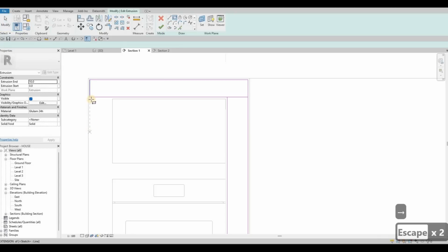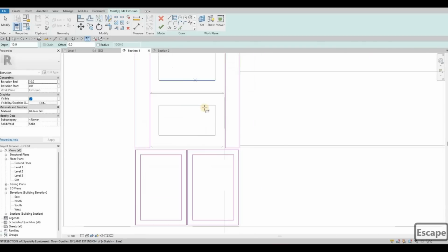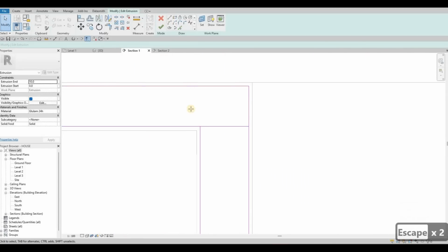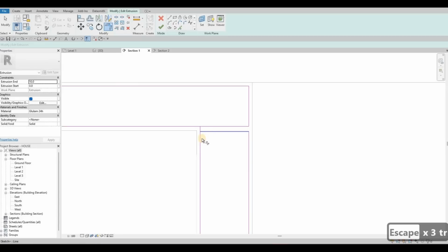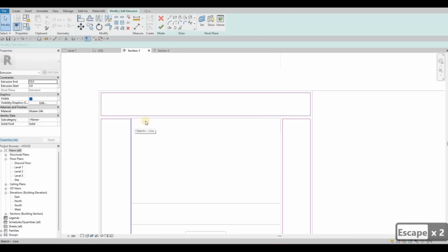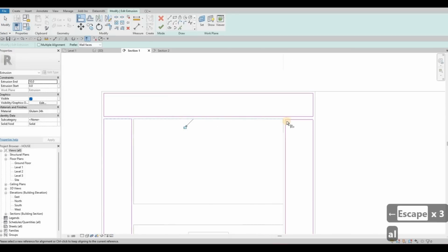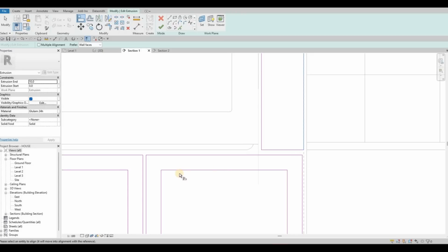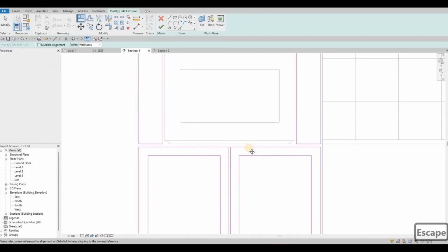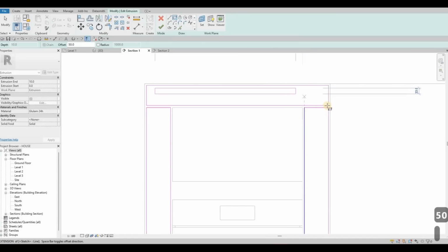And then now I'm going to add this one right here. Then I'm just going to align it all together so that it looks nice. And then here, trim and extend, TR, trim and extend right here. So on this side, I'm going to notch it and then align it here at the top and then align it here. And then on this side, we could align it all together as well so that it becomes consistent. And then here, we could offset this one to 50 and then go from end to end, spacebar if needed.